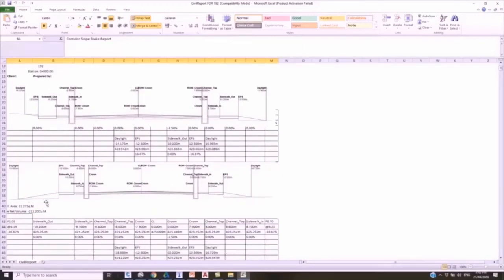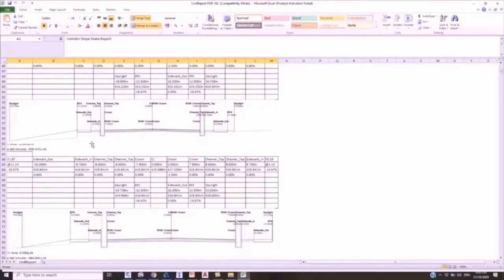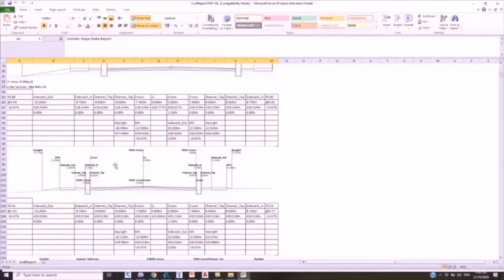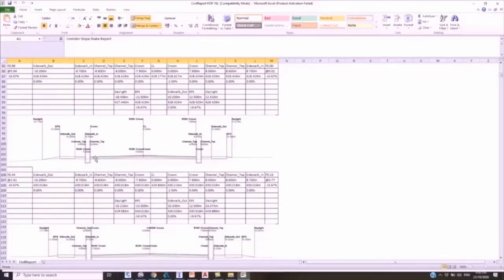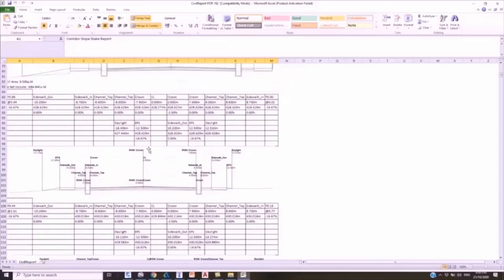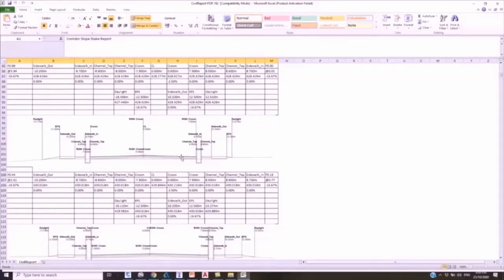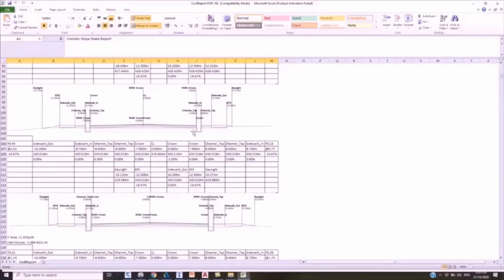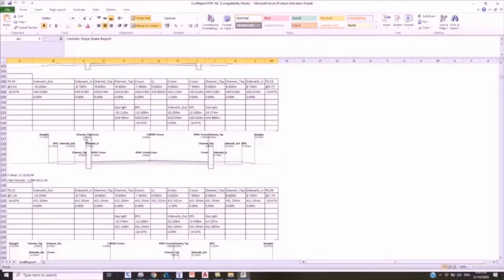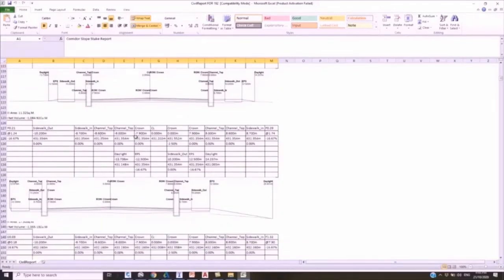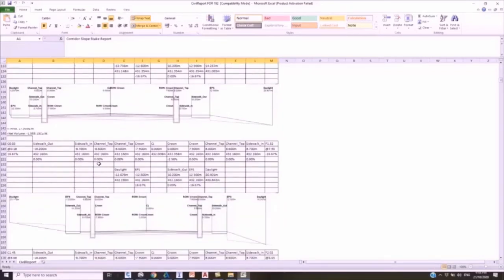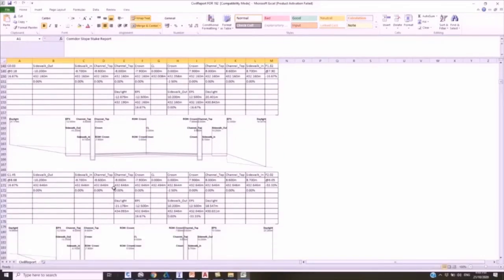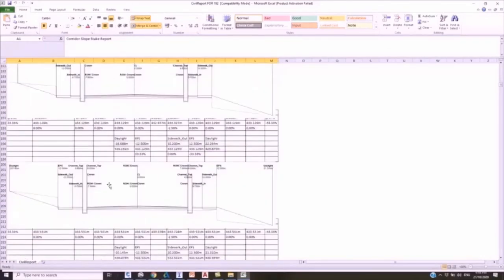At its 20 meters interval of chainage, the information has been shown in line with what we expect to see for the ground level for a corridor build up, including where we have the stormwater drainage, showing the right of way, both top, the sidewalk, and all details reflecting in the descriptions as stated. So this is a clear and very good indication of what is happening for this coordinated site.